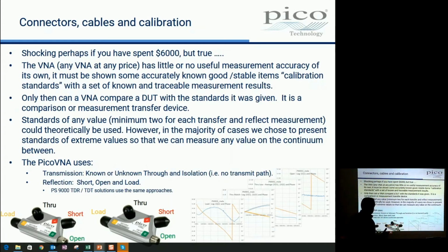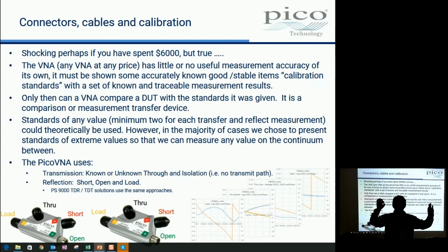What we're going to do is calibrate the VNA, and make it measure not perfection, but these sets of data for each standard. So don't think that when you connect the load you're going to get a perfect flat line. You won't, because it's imperfect in a very well-known way. So what you'll get is a plot of it.